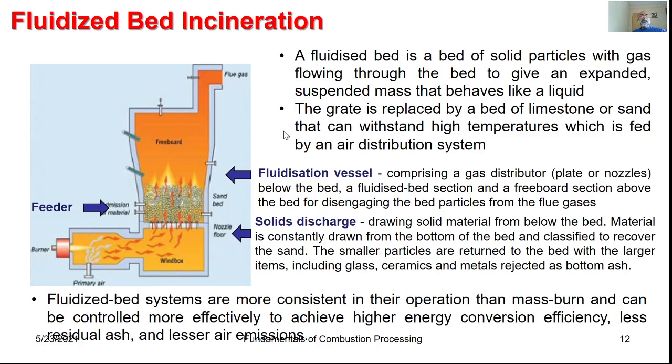Another important technology is the fluidized bed incinerator. It is a bed of solid particles with gas flowing through the bed to give an expanded suspended mass that behaves like a fluid. Here, the grate is replaced by a bed of limestone or sand that can withstand very high temperatures.